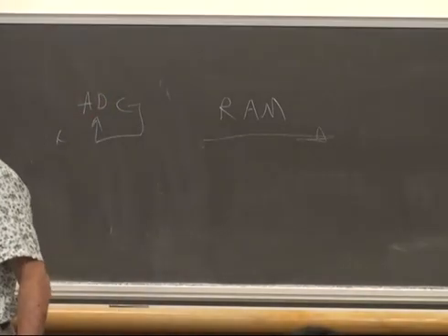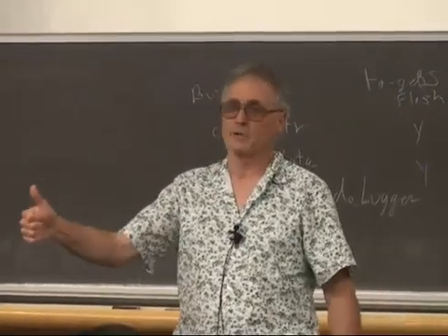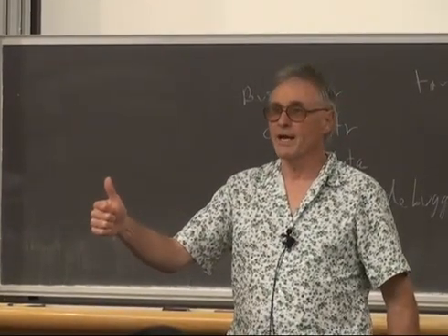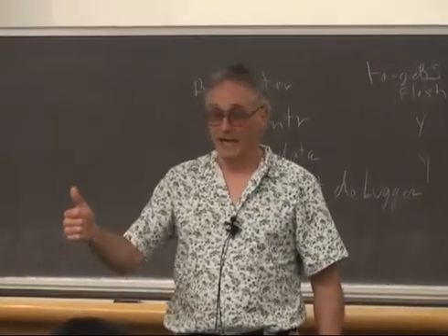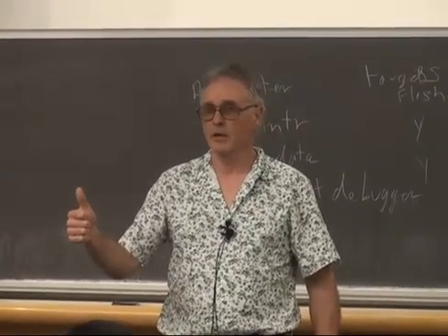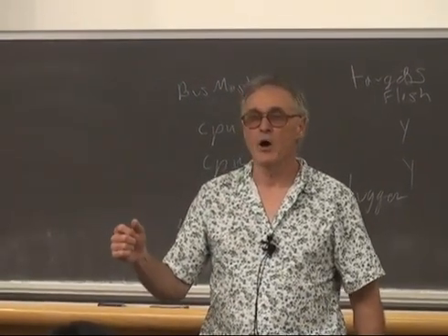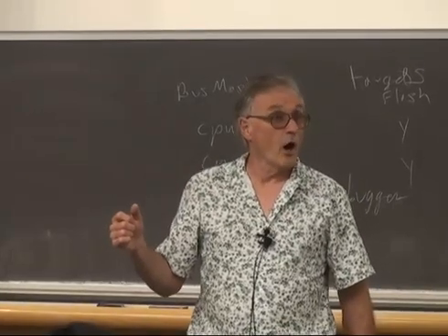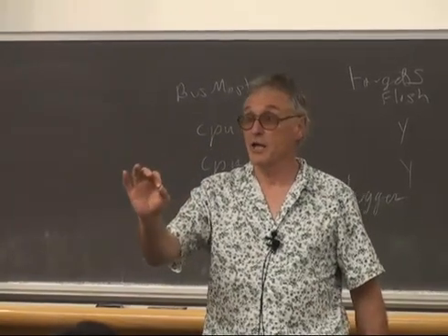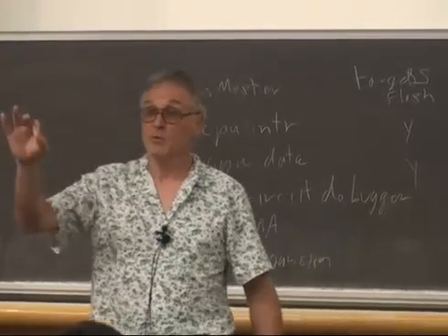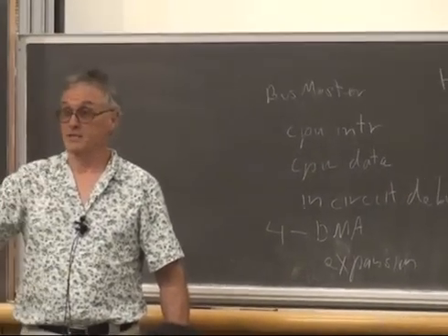There's stop control. You can stop a DMA burst by any interrupt source, or by a software abort command. You can start a DMA burst from any interrupt flag. But here's the weird thing. You don't have to take the interrupt in an interrupt service routine. The DMA hardware will detect the hardware interrupt flag and do the whole start transaction operation in hardware with no interrupt service routine. That's cool. That's zero overhead.